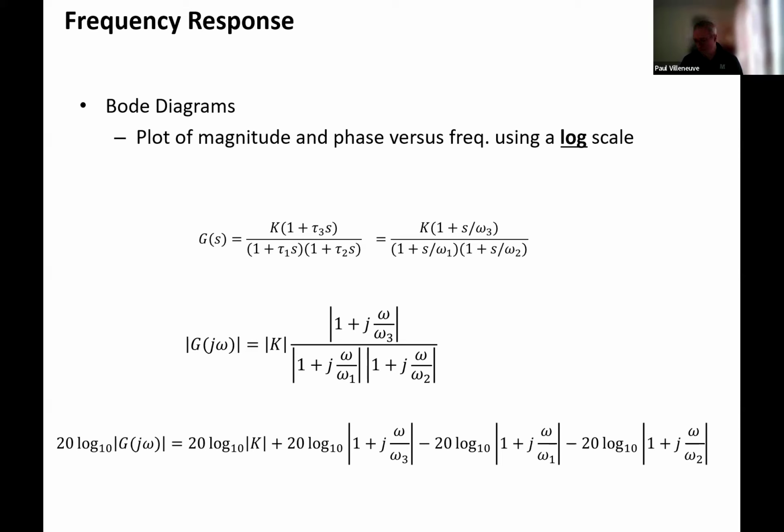We're trying to display more information, which is typically when you would use log paper or semi-log paper, because this is actually going to be semi-log paper. Is this semi-log paper? Let me think about that for a second. Yes, it's semi-logarithmic paper because the x-axis is logarithmic and the y-axis is going to be the standard value. So we use semi-log paper and we plot the frequency using a logarithmic scale, because as we increase our frequency, we look at things as multiples of the frequency.